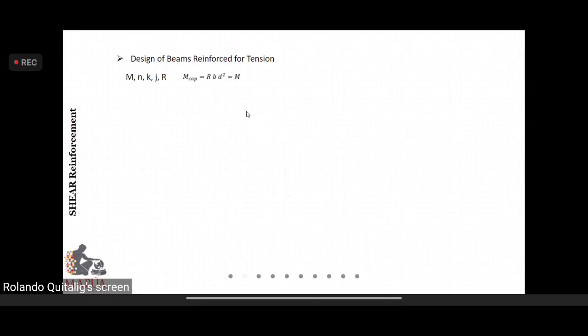And then we are prompted with two unknowns here. We are actually designing the dimensions of the beam. You can either represent this as a function of d or this one as a function of b, by having the guidance of the ideal ratio of 1/2 to 2/3 of d and b.